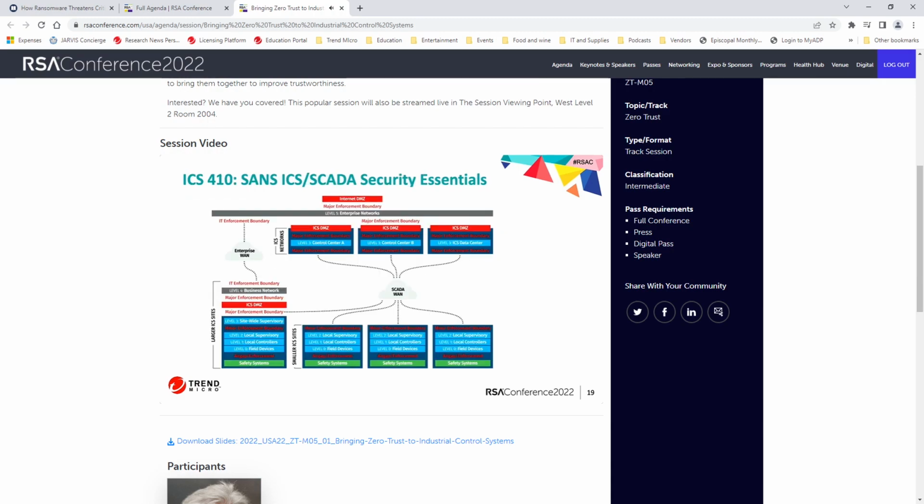More detailed examination. This is from the ICS SCADA group at SANS class on security essentials. The details on this chart tell you what you need to do for local, for large, and for host-centered environments about where to put sensors, where to put firewalls. You want to break things up into segments. You want to minimize the amount of activity. You want to strip out capabilities that are not necessary. Nobody needs to run a compiler in an industrial factory. You don't need to do that stuff. You don't want to be running installs in products that are targets.